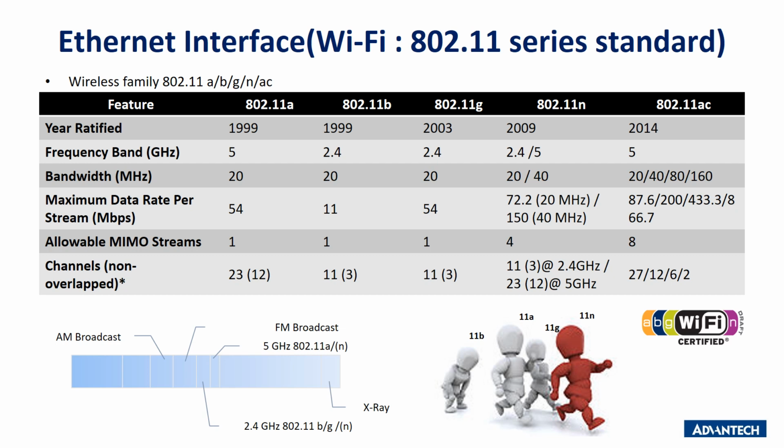The common one is the IEEE 802.11 standard, which is normally called the Wi-Fi protocol. Like the Ethernet communication standard 802.3, there are several types of 802.11. Here is the 802.11 family, and you can easily compare the difference between each protocol. You can find the frequency, bandwidth, and speed are different. The latest is 802.11n. Normally, the wireless interface card or module supports more than one 802.11 protocol. We need to consider this if we need a specific protocol.